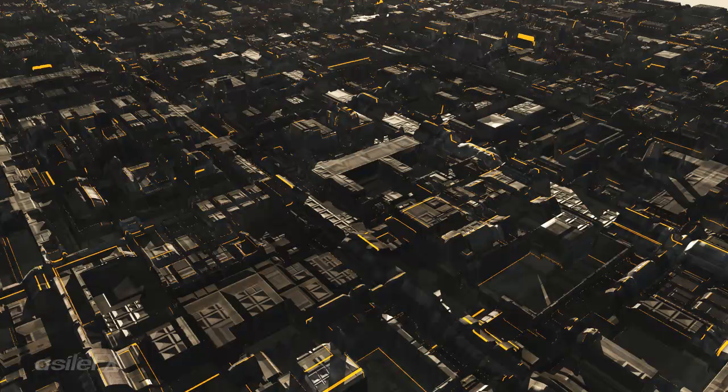And we can set up an alpha, or run an image or a noise or a fractal along the alpha to cut out some of those areas so that we don't have a completely smooth strip if that's not what you're looking for. You could also reduce to a lower range of the slope from 0 and up in order to affect some of the vertical areas. So a lot of different ways to continue forward with that.